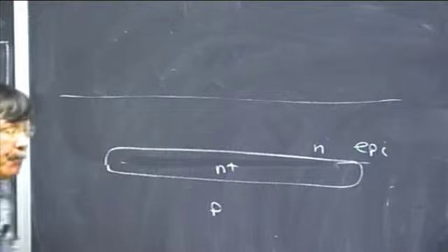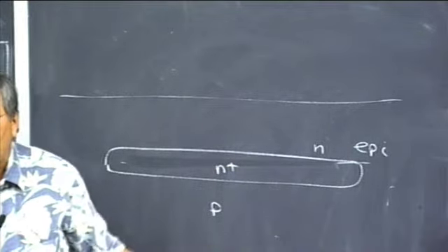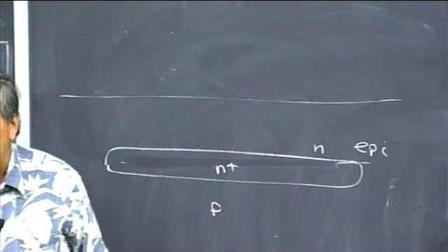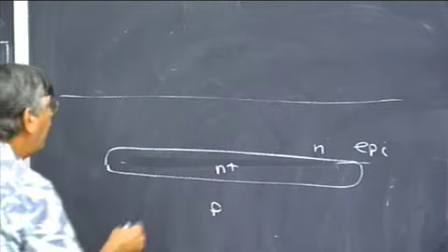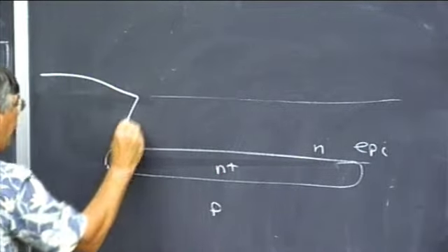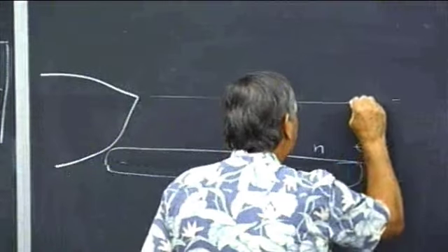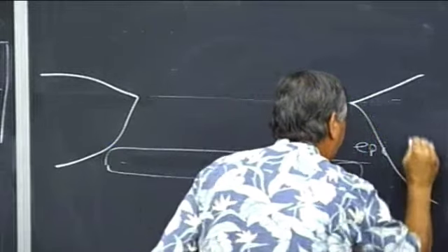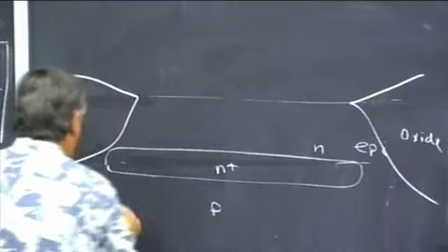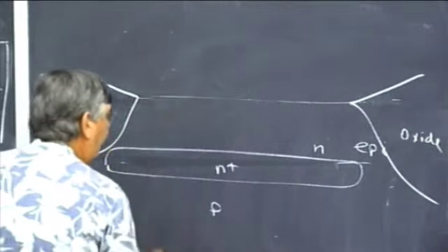All right. If you put down silicon nitride on something and then expose it to oxygen, the silicon nitride, I'm sorry, will block the oxidation. So you can get so-called localized oxidation. So what we're going to do, and you get this weird shape, but I can get a big old thick piece of field oxide, and the oxide is going to completely surround the transistor on all sides. So this is silicon dioxide, and this is going to be mostly an oxide isolated process. And it's going to work a lot better when we're all said and done.